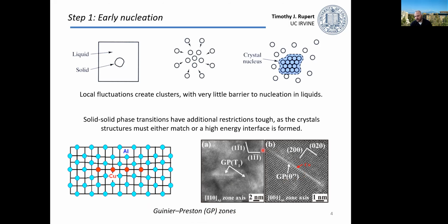And I can see these in the electron microscope. The thing I want to point out here is all of these atoms are projections of atomic rows, atomic columns. If you look, you find that all the columns match up, which tells us that the crystal structure hasn't changed. The fact that these are brighter has to do with the fact that there's a different element located along that GP zone there.